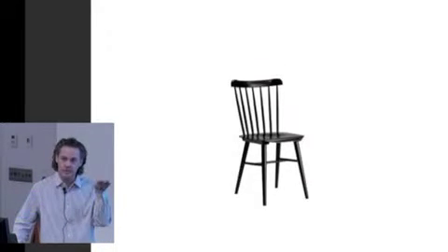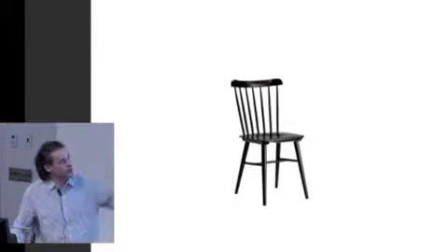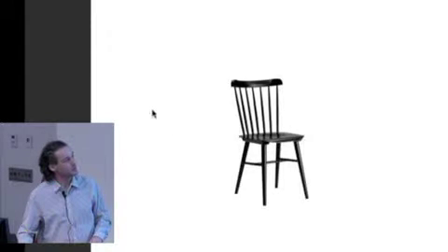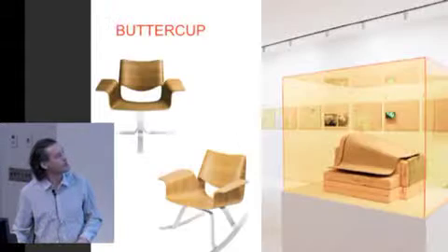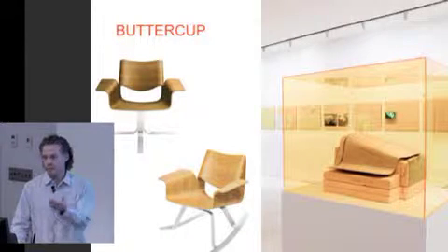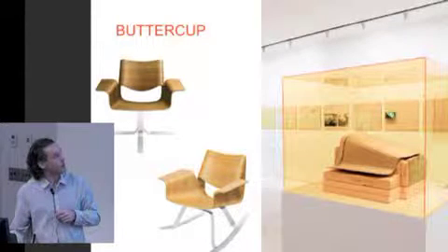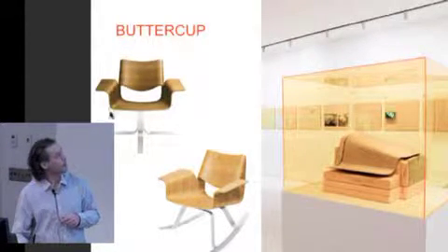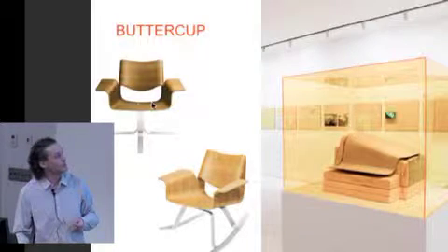But this also then goes backwards in how it's made and how it's put together. So this is what we typically understand as a chair. A chair is made of lots of parts and pieces, and these are all joined together as wood has been joined together for centuries. That's difficult. Those joints are the weak part, as you well know. That's where chairs fail, where they break. And so we tackled this problem of a lounge chair by, rather than joining many different pieces of wood or material together, going to molding as the methodology.